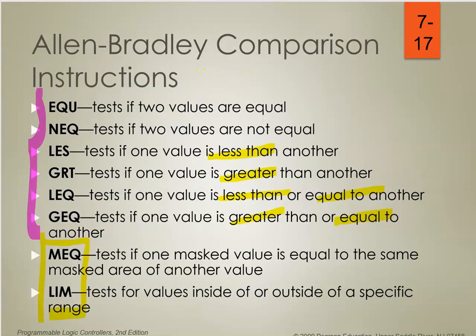Now let's go to MEQ. MEQ stands for masked equal to. So it will test and compare two sources of data that are masked over some of the bits. If the masked areas are equal, then the instruction is true. Otherwise, it is going to be false.